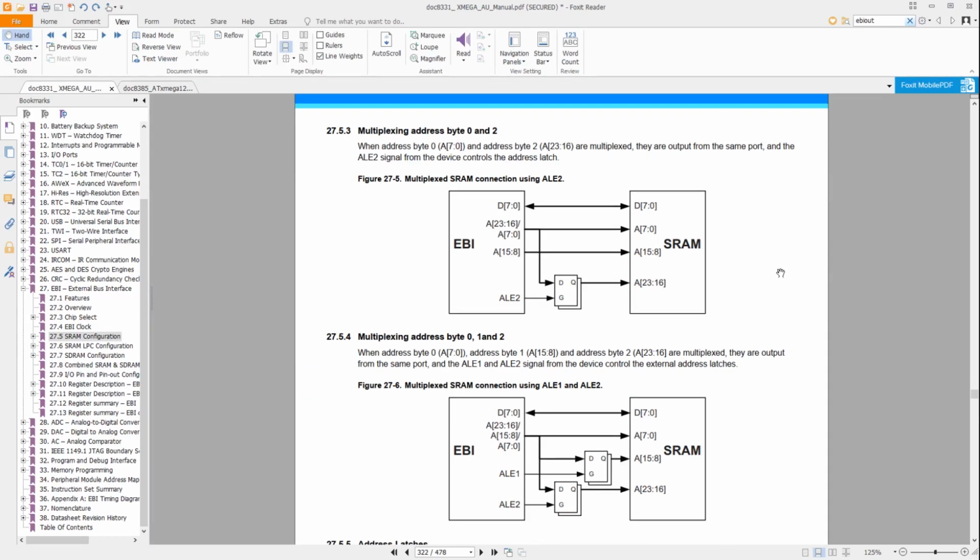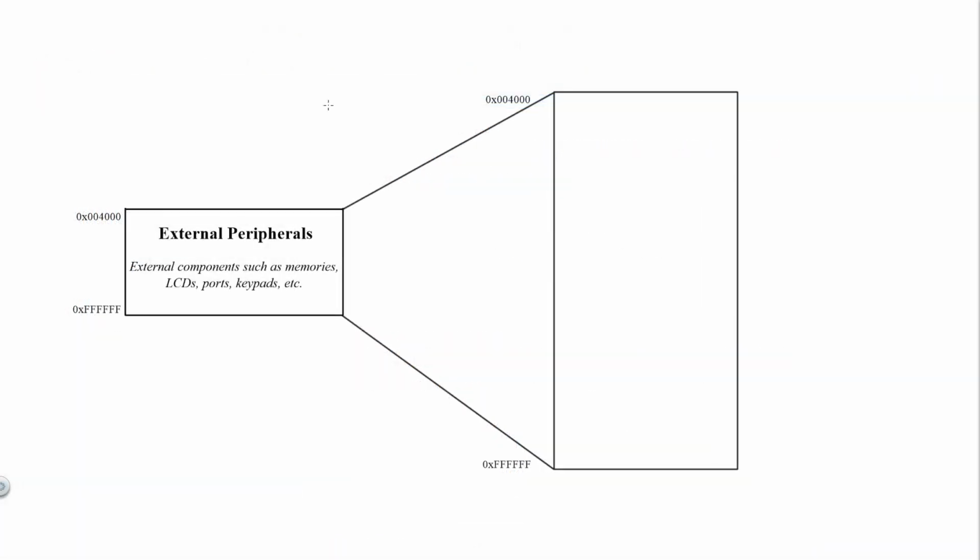You should understand the difference between all of these arrangements as well as when they should be used or not used. The main similarity between these 2 arrangements is that they give you access to all 24 bits of the address, which could be crucial in some applications that use up the majority of the memory map. After you decide which configuration and arrangement you're going to use, you need to decide where you're going to place your device within the memory map.